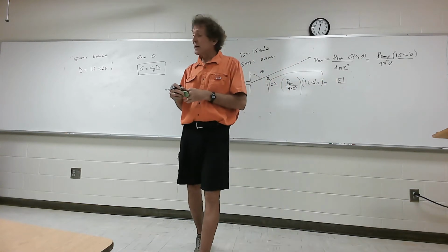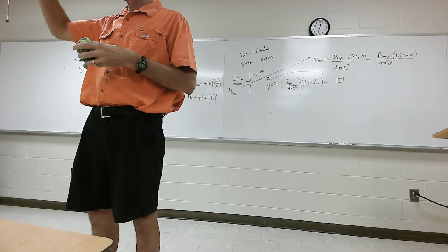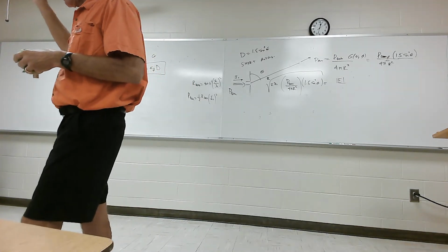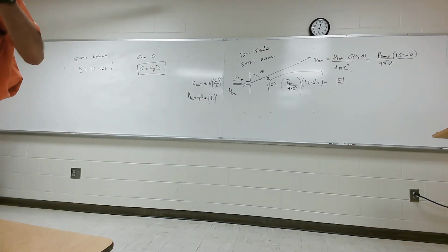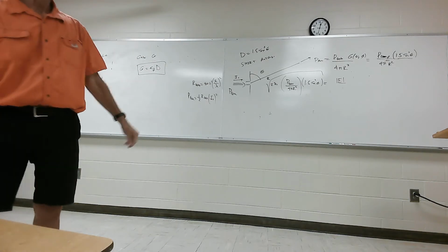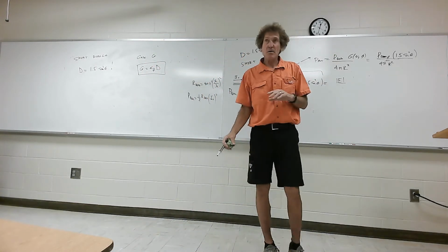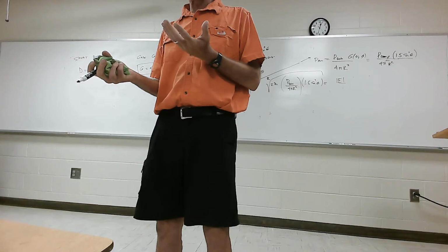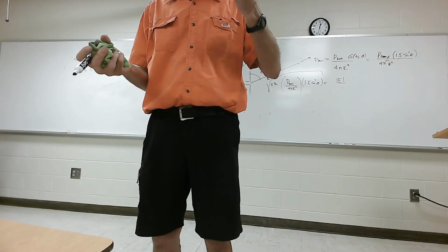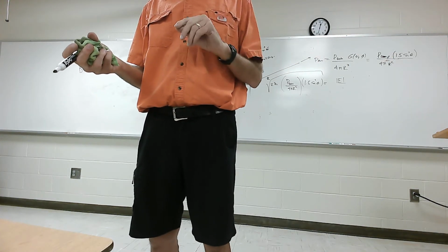Remember in the beginning, the equation for the E field? j eta beta L over 4 pi r, e to the minus j beta r times sine of theta. There's a lot more that can go wrong with that equation than what I'm showing you here, because most of you have a fairly good appreciation for the transmitted power over 4 pi r squared as the isotropic power density. Then the only other thing you have to do is multiply it by the gain of whatever antenna you want. And now you have the power density at a given range and angle.